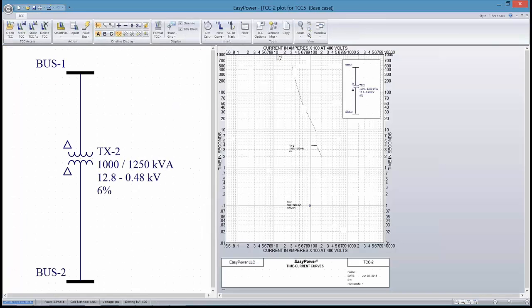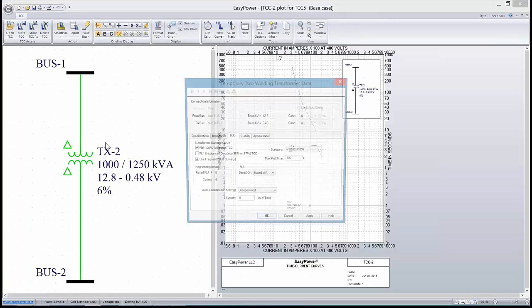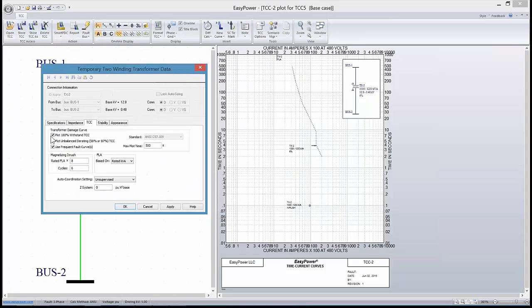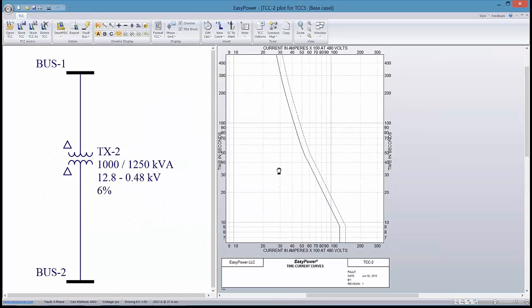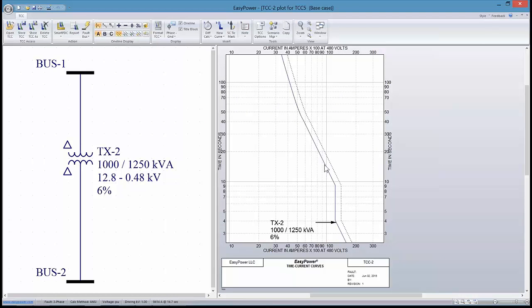All right, the point I'm trying to get to is now if I go to the coordination focus, we plot this curve. Now it's a delta delta. The tool knows this, and as I open it up and then plot this unbalanced curve, you'll see now instead of a 58% difference, it's looking at an 85% difference between these two plots. So this would be what's used on a delta-delta comparison.